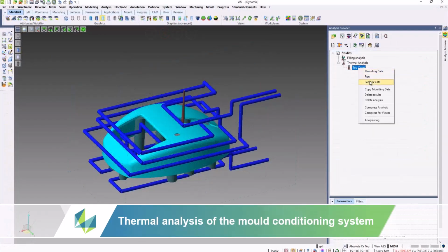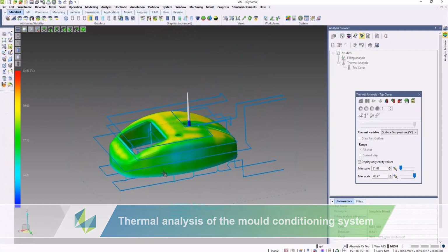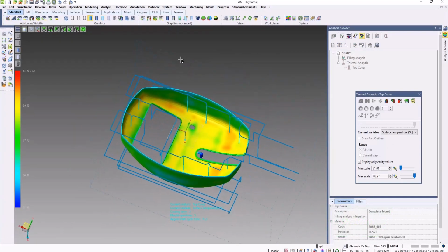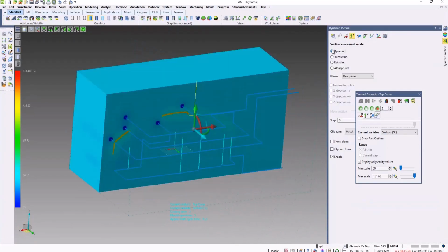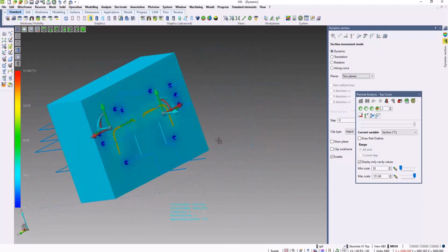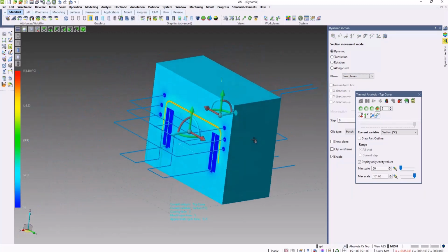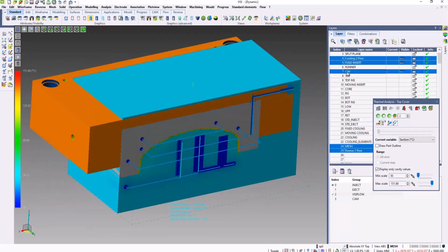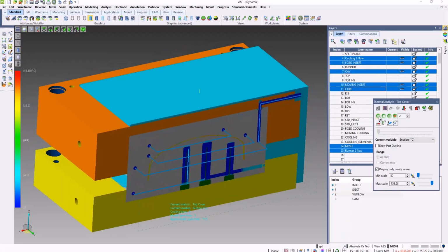Thermal simulations predict the behavior of mold cooling and enable us to analyze the cooling performance for alternative solutions. We can try out different circuit combinations and variations. Ultimately, the customer can also analyze how the temperature is dissipated throughout the mold assembly and determine the thermal effects on the plates and components surrounding the injection.